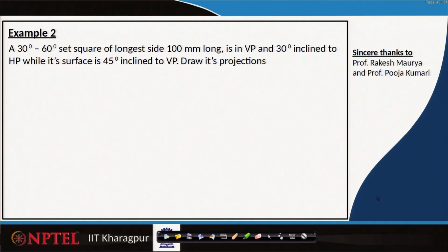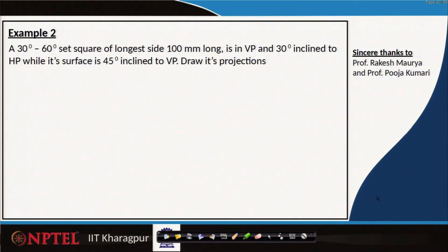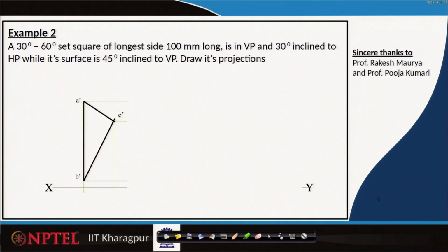So, if I am projecting that onto horizontal plane, there is a 30 degrees thing, and its entire surface right now is perpendicular to the vertical plane. But now, if we are making something like 45 degrees in this direction, how does that really look in the projected planes, like normal planes, top side planes? So, that is the thing that we are trying to construct. Let us look at it step by step.